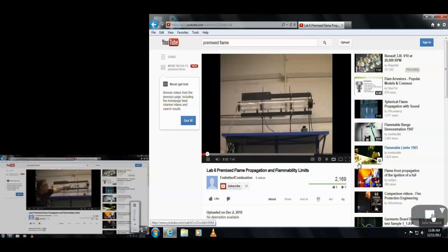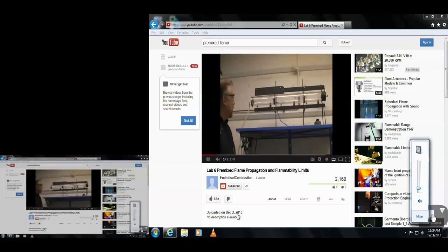On the other end, we've got an igniter on the open end, and throughout the volume, we have 5 thermocouples and 5 photosensors. So we're able to look at the propagation of the flame as it comes from the open end through to the closed end. We're going to be looking at the flame speed and the temperature of the flame.